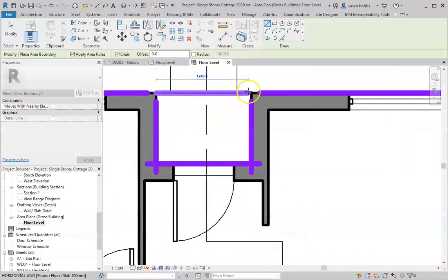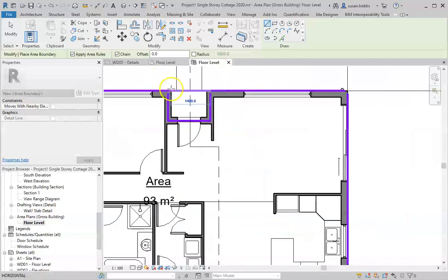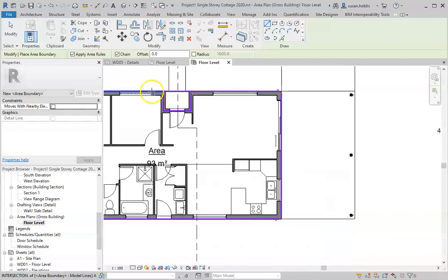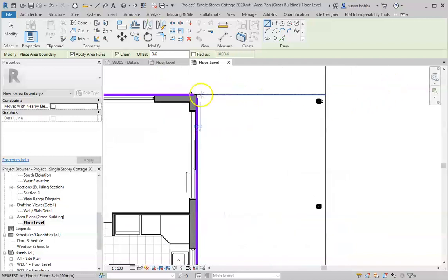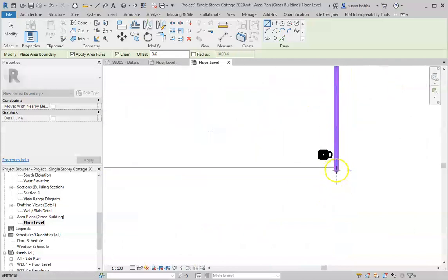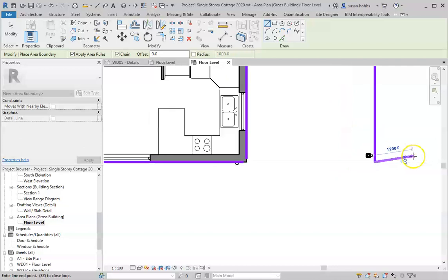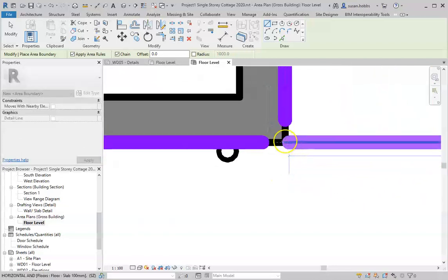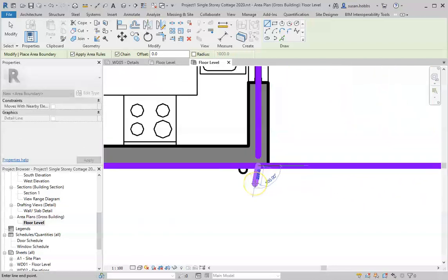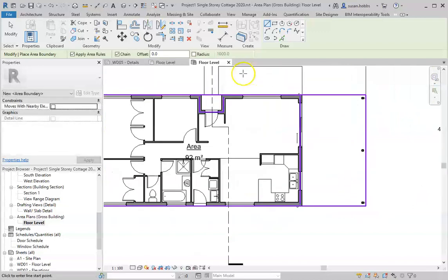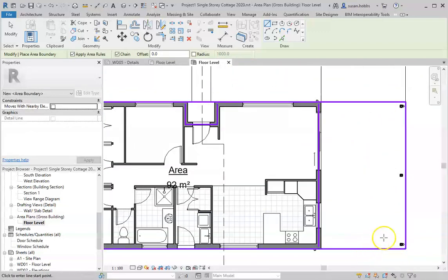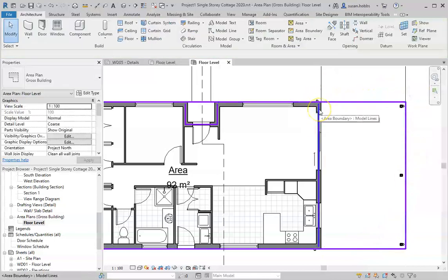So click on the corner there, on the other corner. Click Escape just to leave those there, and then we'll place the remaining 3 lines. Make sure you use the snaps so that this stays very accurate. All right, so we have placed in these extra boundary lines. This is where you can see a little bit of what I was starting to say, that Revit doesn't quite do exactly what we want it to do every time.